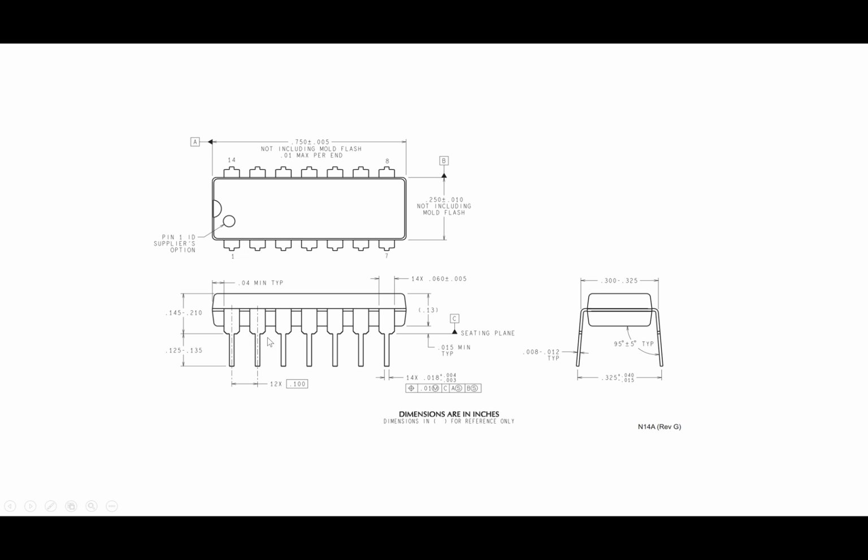So in this case, this would be a through-hole component where I want to have these pins going through the board. I need to make sure that holes are placed in the right spots and that the pads placed around those holes are of the right width, right? So I need to have this information about the footprint of the component to make sure that the board itself is set up properly.